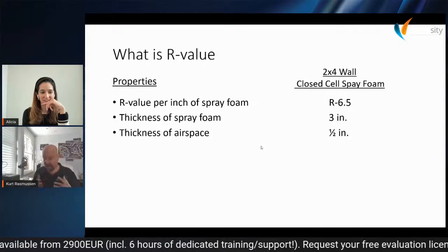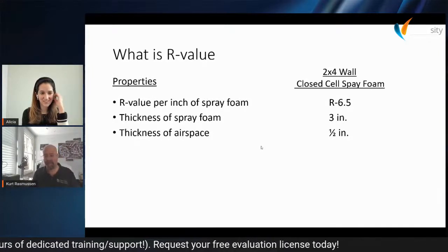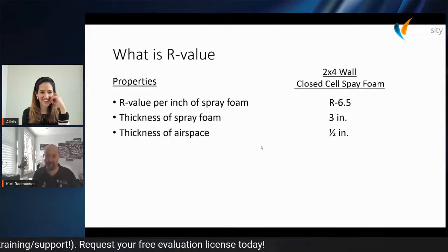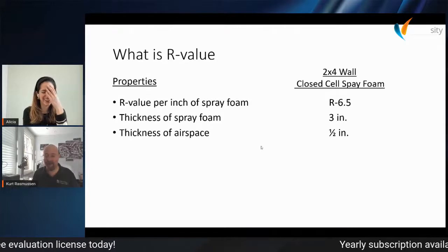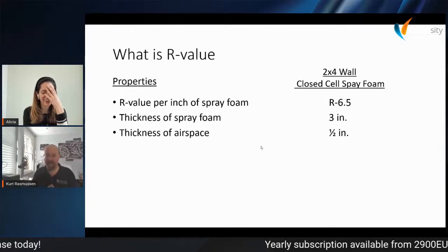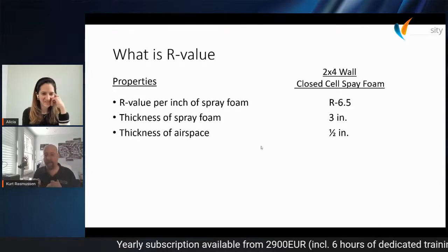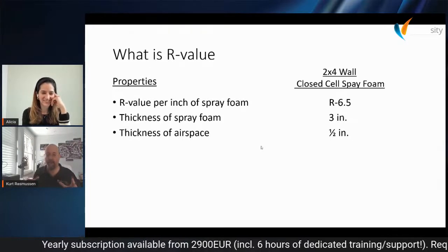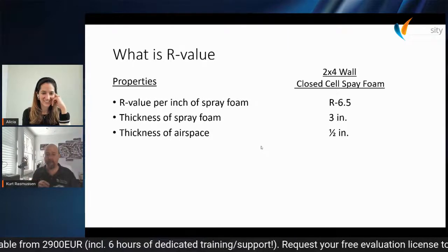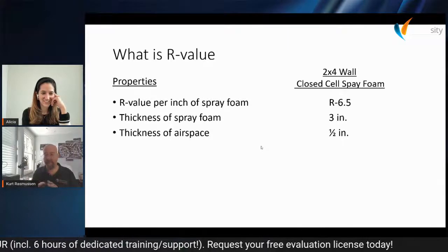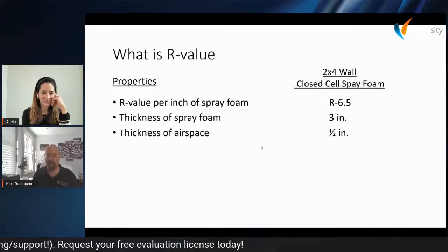Yeah. Then he started saying, well, we have a 1/2 inch of tolerance. Now, I'm all about tolerance. I've done aerial mapping, and I know national mapping standards in the United States is I have to be 90% accurate, or I have to be accurate to half a contour interval on 90% of my project. So when he says 1/2 inch tolerance, I would expect that he has 10% that he would be allowed to be less than that, that 1/2 inch that we're looking for.